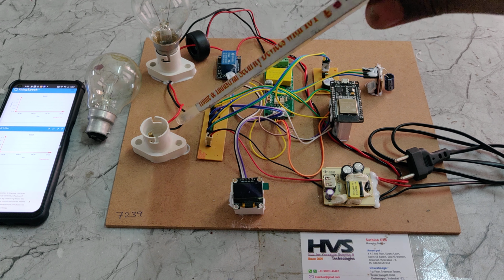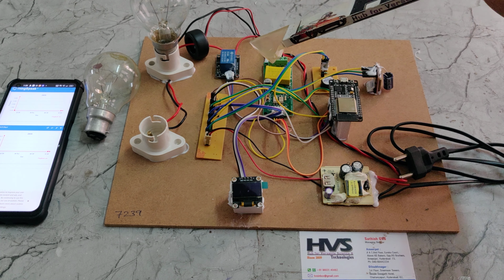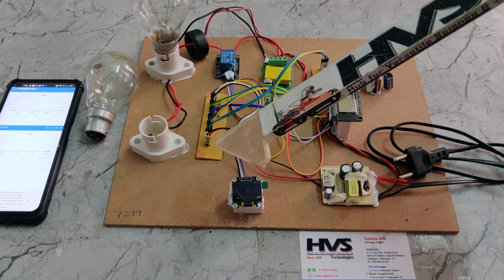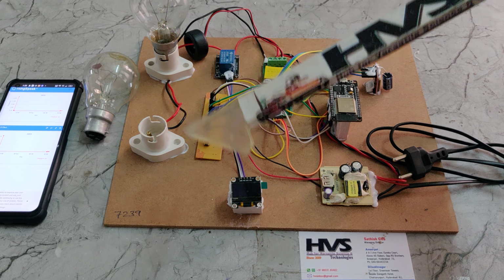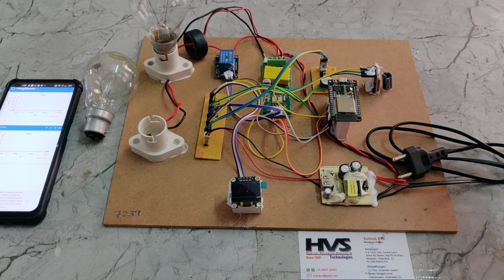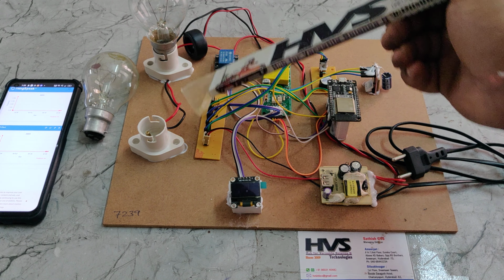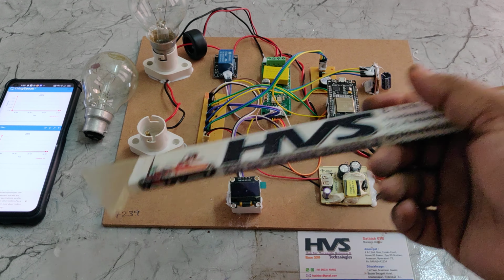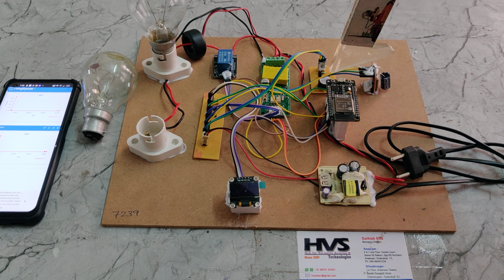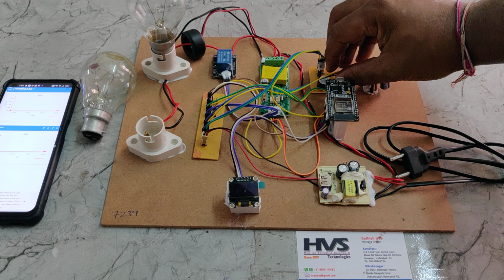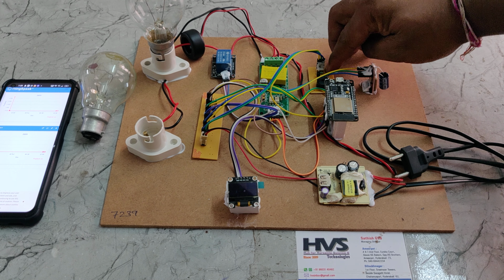These loads can be handled up to a maximum of 100 amps, but for demonstration purposes we kept the limit for the high load alert at 150 watts. Whenever the connected load is more than 150 watts, the system will isolate the power supply to these loads and also send SMS alerts to the registered phone number using this GSM module. And there is a buzzer to provide audible alerts whenever an abnormality of load is detected, when it crosses the threshold value.